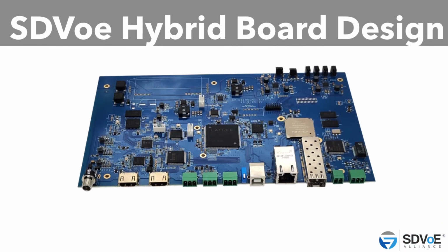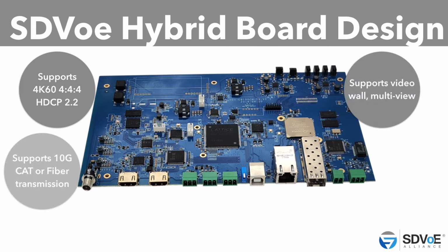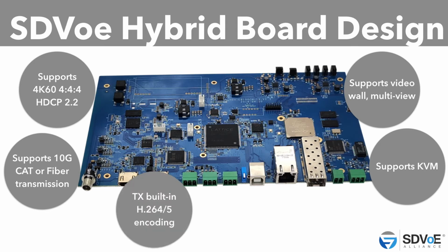So this is our board design. It supports all the SDVoE features: 4K 60 4:4:4, HDCP 2.2, video wall, and multi-view. We have options for both CAT copper and fiber, it supports USB for the KVM function, and we have H.265 built into our transmitter.